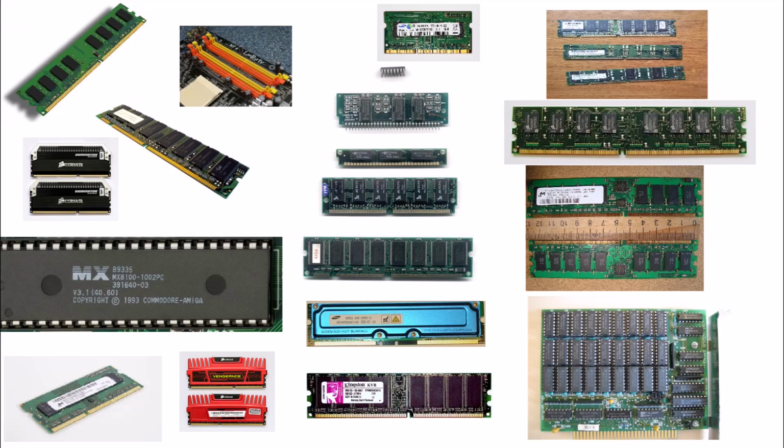EEPROM memory, permanent memory with electrical write and erase capability. The number of erase and programming cycles is limited from approximately 10,000 to 100,000 times. Flash memory, a type of EEPROM, faster to write. Nowadays, it is increasingly used due to its low manufacturing cost and ease of programming. As in the case of EEPROM memory, no specialized equipment is needed to reprogram it, just appropriate software. Like EEPROM, the number of erase and write cycles is limited.